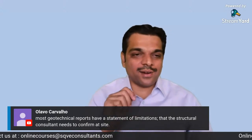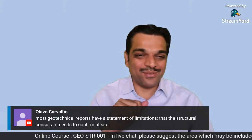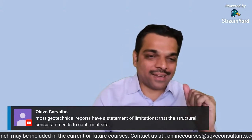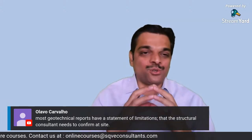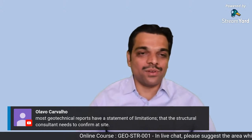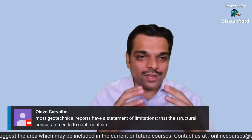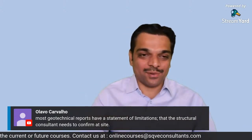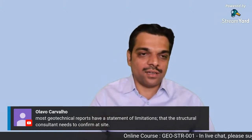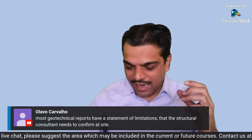Olao is telling that most geotechnical reports have a statement of limitations that the structural consultant needs to confirm at site. Yeah, I think that's where, generally, the practice we were following, as I told you, is that there has to be a joint visit of the structural engineer and geotechnical engineer on the site whenever we have excavated the soil up to the foundation level. It may happen, and I have experienced in a few projects, that the soil which we had conceived, or which was mentioned in the geotechnical investigation report, was not there for particular foundations or a particular localized area. Then we had to revisit the entire foundation design for those localized areas. And if I am going to a higher depth for the localized area,